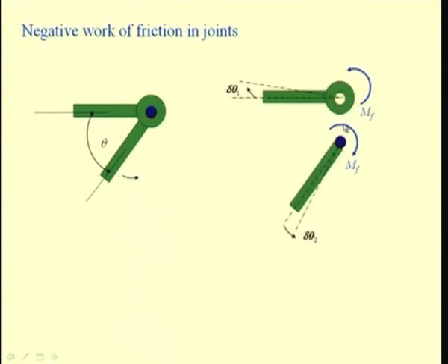So, for a better understanding, here in this picture we have dismembered the assembly in order to account for this frictional moment, because if we take the free body diagram of this complete assembly, then the frictional moment cannot be accounted for. So, we have to dismember in order to account for these forces, which now become active forces, thus doing the negative work in each of these bodies.